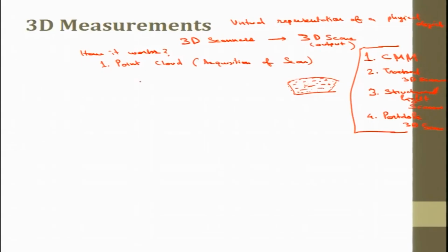Sometimes there are structured components, like a circle, a cone, a plane, a rectangle. When these known shapes are there, those are known as structured forms. This is a kind of free form. If you know about curves, Bezier curves, B-spline curves, those are also there, but nowadays those are not very significant. Even for free forms, any curvature that we need is quite possible to scan using 3D scanners. So, the first point is the point cloud.